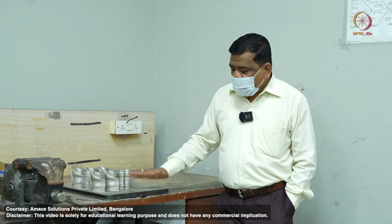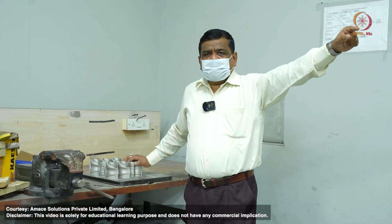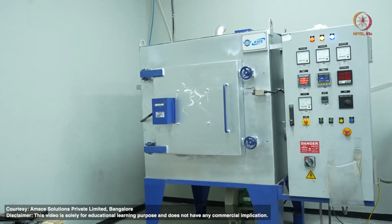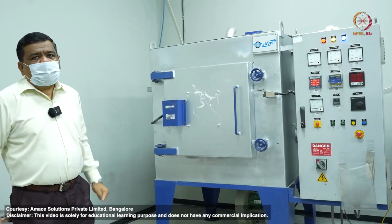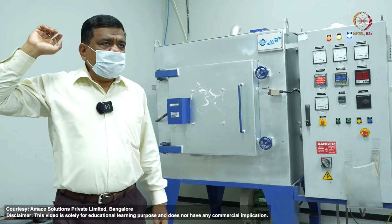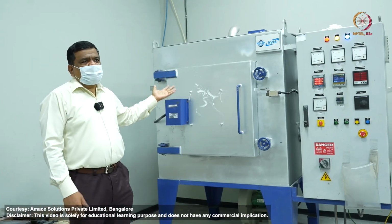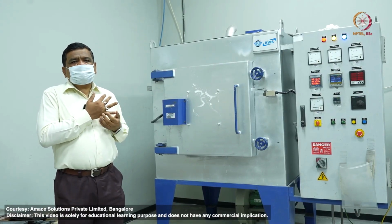These are the as-additively-manufactured implants. Now these implants will go for further post-processing. So this is the heat treatment furnace, you can see. This heat treatment furnace can go up to 1200 degrees Celsius, and then it can be heat treated for a longer time period as per the requirement. After the heat treatment, the samples will be grit blasted. This heat treatment furnace is used for all metallic structures, whether it's aluminum alloys, stainless steel, titanium alloys or cobalt chrome alloys.